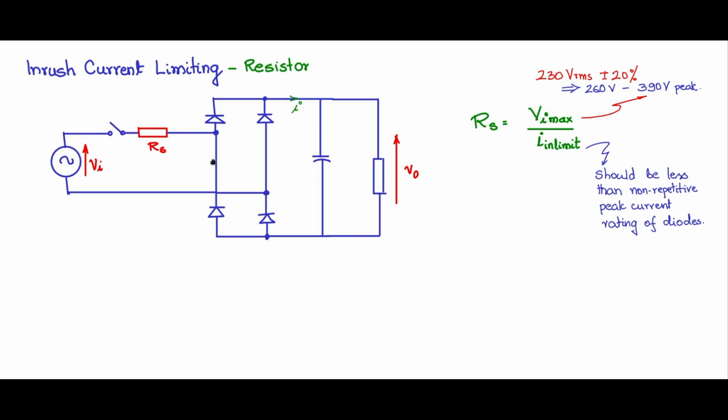So if I mark the voltage measurement like this, that is, you are keeping the common probe here and the positive of the probe here, you get VRS because there is a current I in flowing through it, and I in flows in this fashion as we saw in the simulation, in steady state. The job of Rs is only during the starting inrush current.